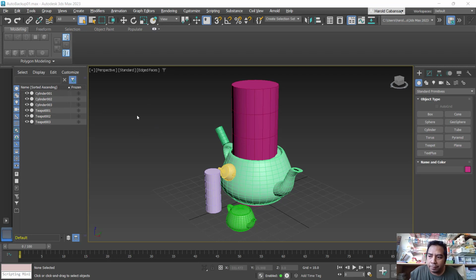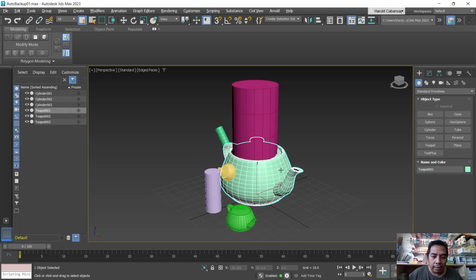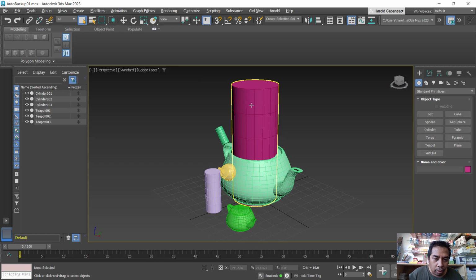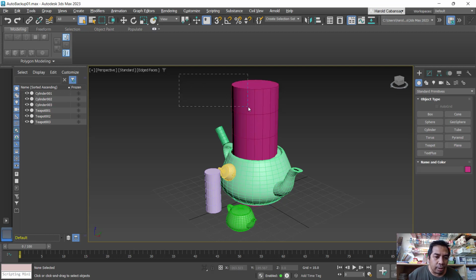First, the selection, so that we can use the tools. First off, how do you select objects here in 3ds Max? Well, you can select in various ways, such as a simple click and you will be able to select objects, or a simple click and drag. Okay, so this is what you call picking. When you pick an object or when you select by clicking, you pick it. Click and drag is the region select.